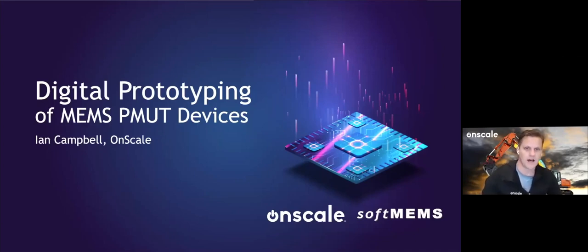Then you would take that layout, and just like Marianne just showed you, you would use SoftMEMS, MEMS-Pro to create fab accurate 3D models of that layout, and not just the nominal values, but also factoring in some of the tolerances, because every design variable here, including the top-down orientation, the layout itself, and the thickness of each process step or layer, will have a tolerance associated with it.